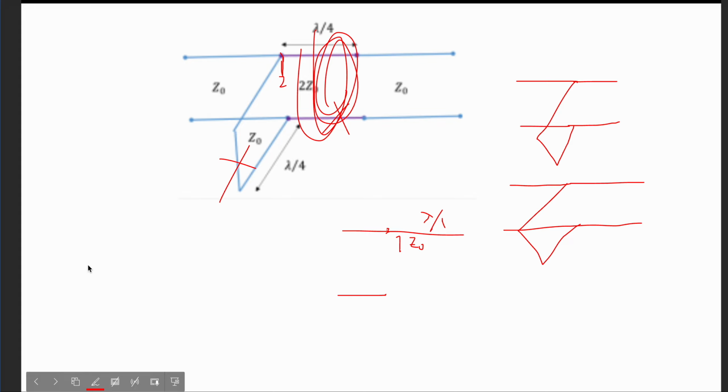Okay, let's solve it. Again, you have two ports, and I want the answer. You need to tell me these are the ports, and then you connected one stub, and this is the other port, which is again Z0. There is no transmission line here. Suppose this stub has a characteristic impedance of, let's simplify, Z0 only, but it has a length of lambda by 8.